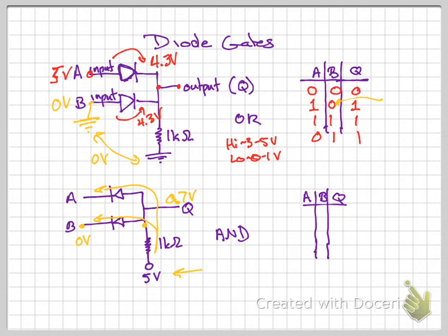So what we're really doing with Q in either gate, Q is simply measuring the voltage at the point where that wire is attached, right? In the OR gate, the top one, Q is simply measuring the voltage right here, and in the AND gate, the bottom one, Q is measuring the voltage right here. That's what we're doing. We're just measuring the voltage with a large impedance so that we're not affecting the circuit.